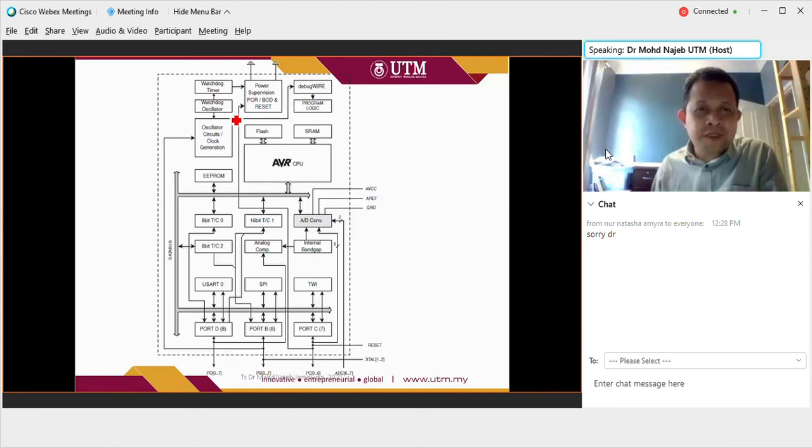Monitoring something. So when something happens, it will react, it will take action, right? So watchdog oscillator, watchdog timer, right? Usually, for example, if your oscillator fails to function, or something happens, maybe overheating, the watchdog oscillator will be aware of this, and it will stop everything from functioning, right? It will just stop everything from functioning.